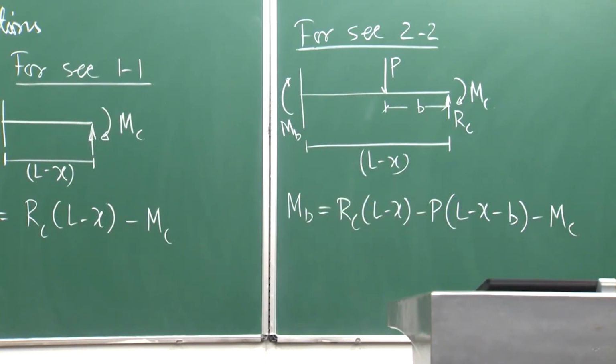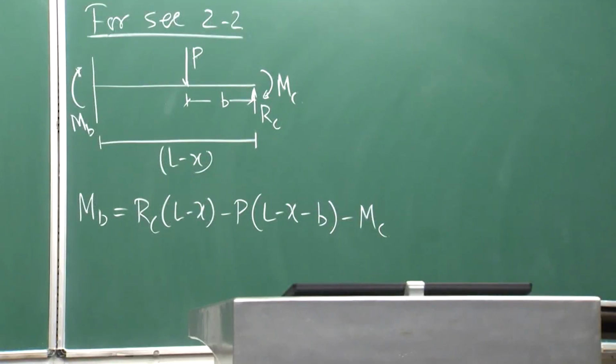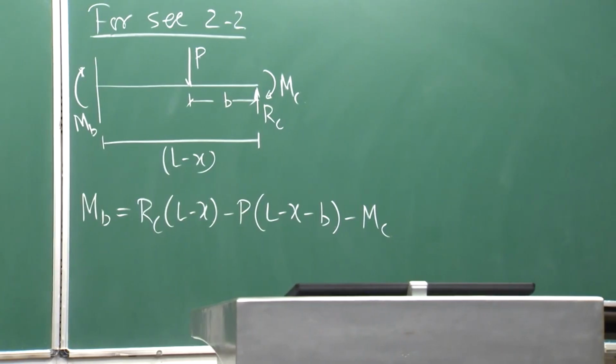And as we discussed in the previous lectures, we will not be considering the contribution of shear force in the deflection calculation, because that is negligible. The strain energy computed based on shear force will be negligible as compared to the strain energy coming from the bending moment. That we have already discussed. So, we are neglecting that part. This is the expression for bending moment.